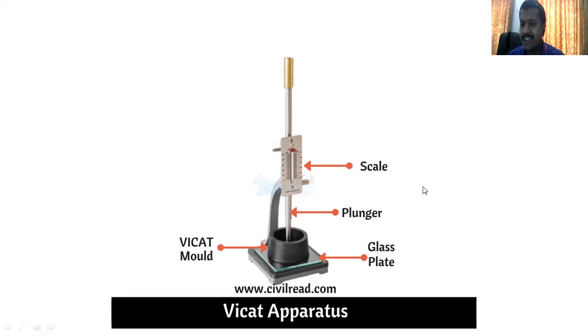In interviews, let me remind you, this question was asked many times. What question they are going to ask you, I will discuss, because the same question was asked to me in one of my interviews also. Okay, what they are going to ask you: sir, what are the physical properties of the cement? Now your answer is, sir, which tests we are going to conduct to know the physical properties of the cement? Maybe your answer is like this: fineness test, consistency, setting time, soundness, or it may be the compressive strength and so on.